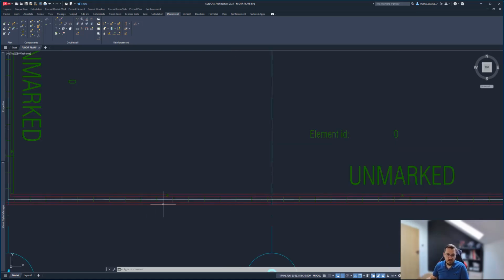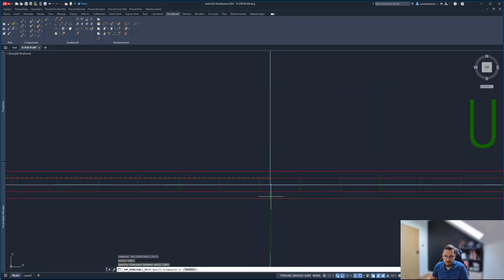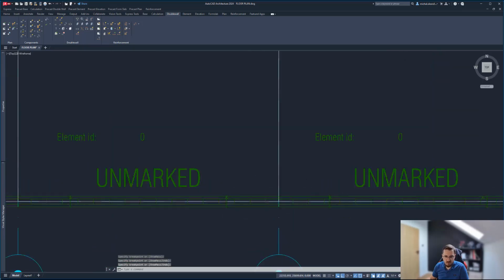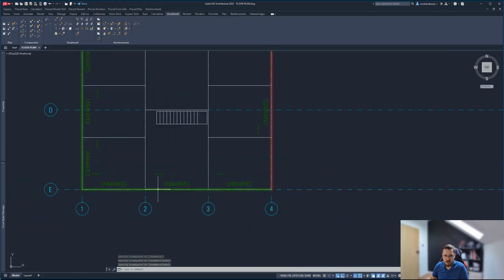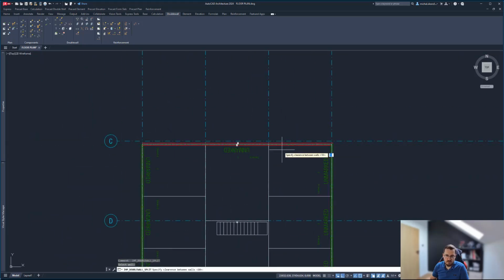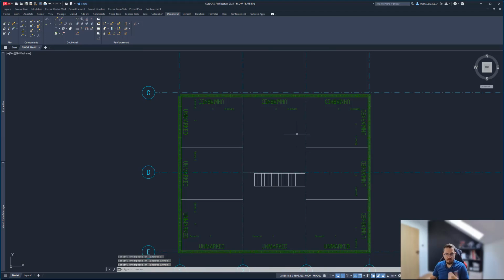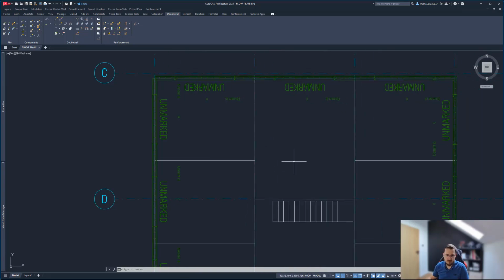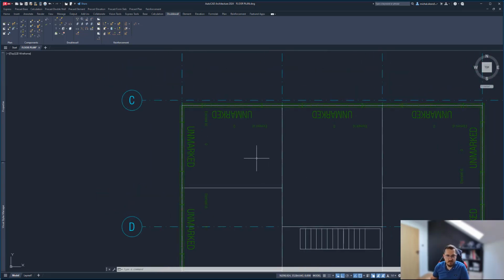If they are too big, then it's just a matter of actually splitting them. And to split them, we use this option. So let me select a wall, clearance between the walls, and click like that, and walls are now split and divided, lifts are added, all good. So I'll do the same for those walls, split, split, okay, and the last one, then split and split, enter. Everything's green, everything's okay. There's no red girders, which means that the girders are placed correctly. We didn't split anything in a silly place.